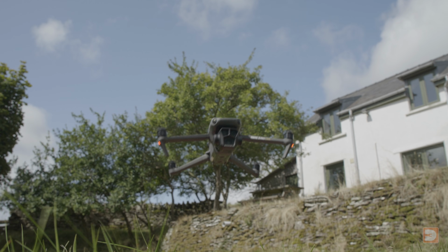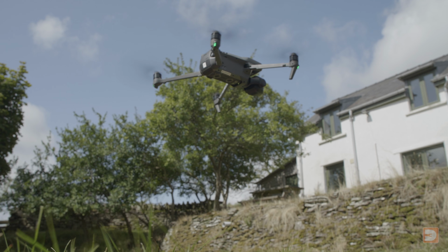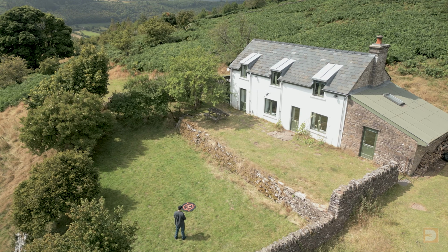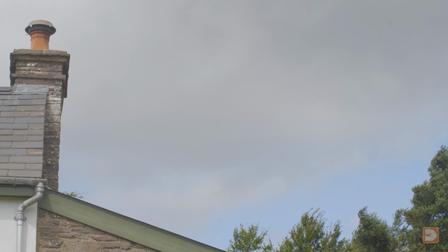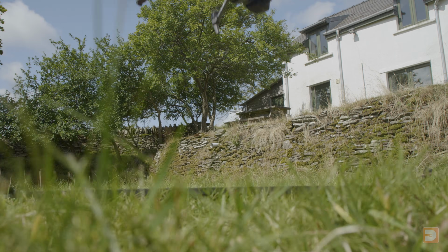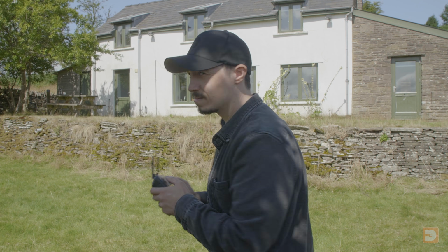Whether using a handheld camera or a drone, capturing photos from every angle is the key to photogrammetry. With a drone, you can either circle around the building at different heights, snapping photos every 10 degrees, or you could ascend vertically, taking photos at regular intervals, and then rotate and repeat. Alright, well, let's see how that scan comes out.